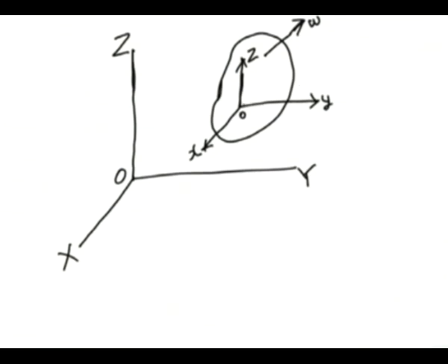So, that means we have attached an axis system which remains parallel to XYZ. Then the velocity of a point P with respect to O may be written as Vp is equal to Vo plus omega cross R PO, small o. So, you get Vp is equal to Vo plus omega cross this one,